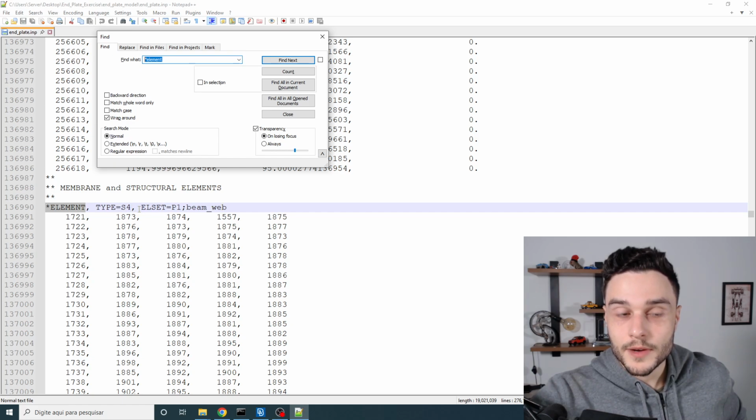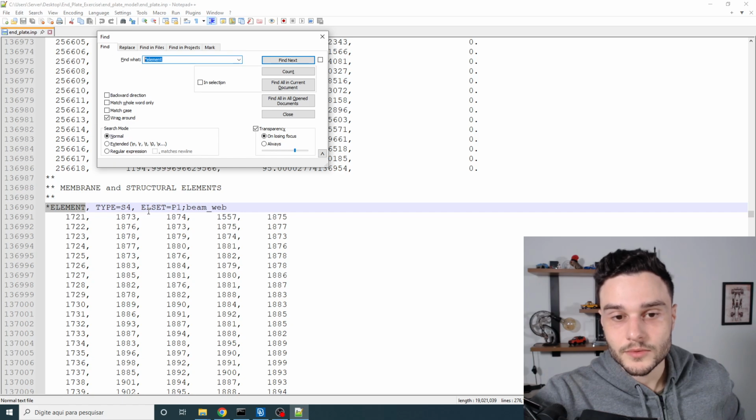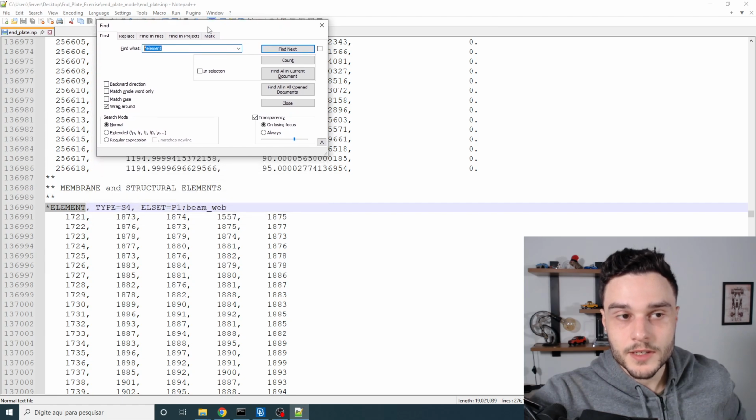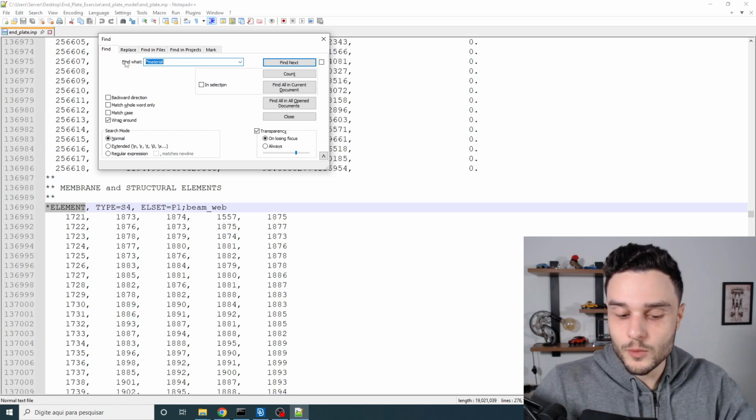And this is a good type of element for this analysis because you're going to see that we're going to have large strains occurring, and this element allows finite strain. Remember that finite strain means large strains. It uses a finite strain tensor in its formulation instead of an infinitesimal strain tensor. Anyways, this is something related to theory that we have learned in detail previously in this course. Well, I'm not going to see everything in this file. Let's just study what is more important.